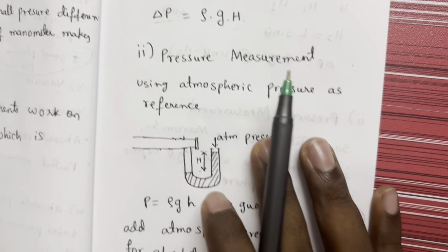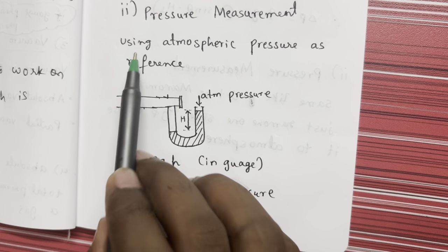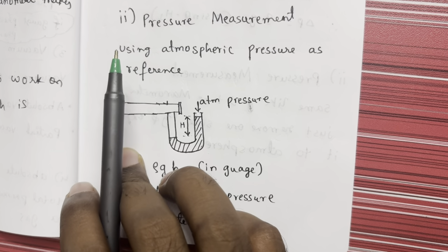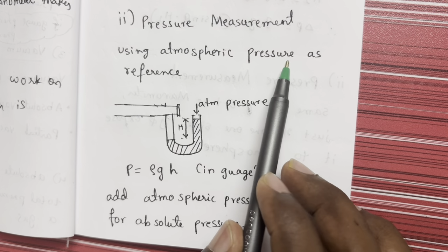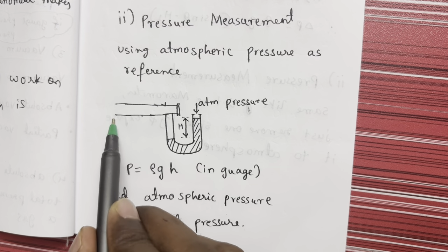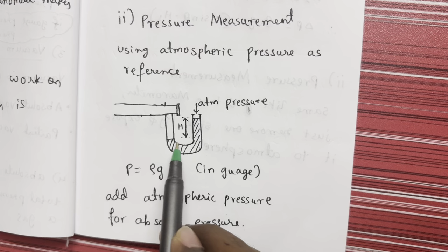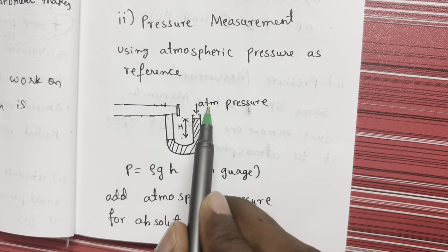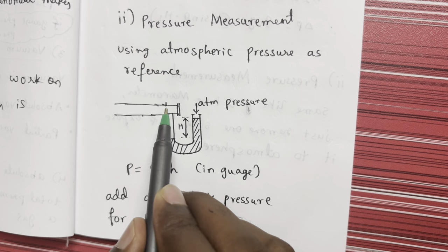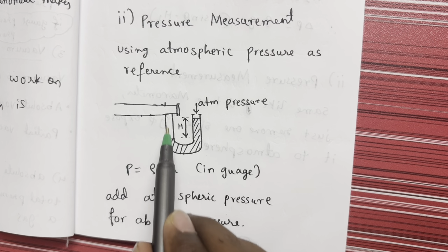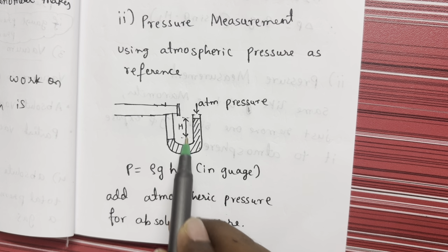Now I just want to find out only pressure. For that, what do I have to do? Here I need to take one reference point. So I will take atmospheric pressure as the reference point. Let's say I have this pipeline and it ends here. Here I connect a U-tube manometer. One side of the U-tube manometer I expose to atmosphere, and since the pipe has higher pressure, it will push the liquid downwards, and again it creates a height difference.